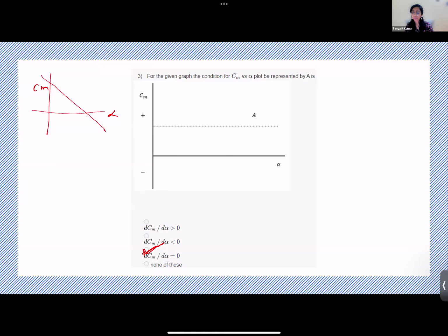For a positive disturbance in angle of attack, negative CM is generated. Yes. So imagine your aircraft is flying and it's subject to a positive increase in angle of attack. To restore this disturbance, you need pitch down. You need negative CM, right? So if your aircraft is inherently stable, it will produce a pitch down moment automatically. That's why you require CM alpha to be less than 0. That's perfect. Okay. Did the others understand what he has said?